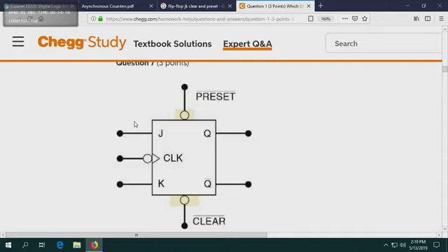Remember we did this when we were doing multiplexers and decoders. There was active low enable, right? Now, what preset does is it makes the flip-flop store the number 1, Q equals 1. But you'll be going, hey, this starts to look very familiar. If we make J equals 1 and K equals 0, it will do the same thing. Why do we need another 2 extra lines over there?